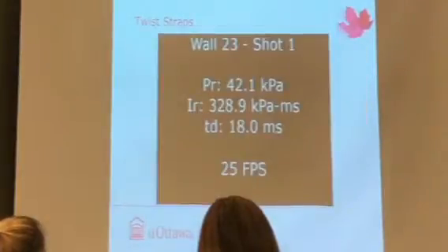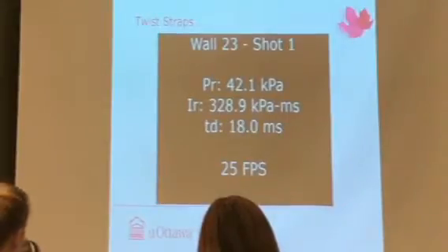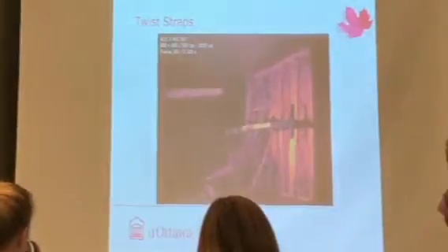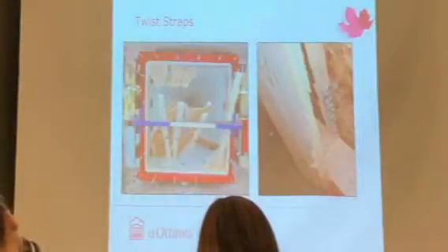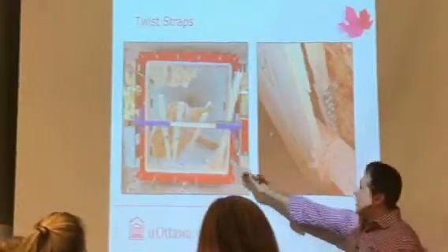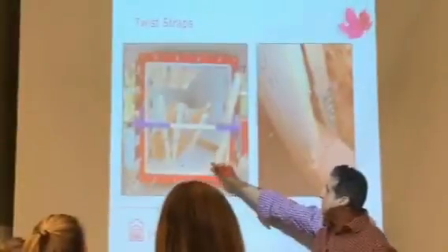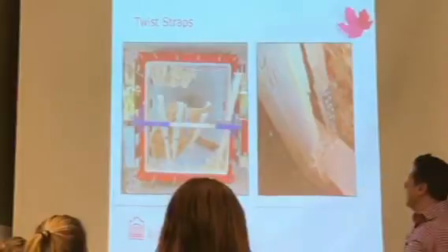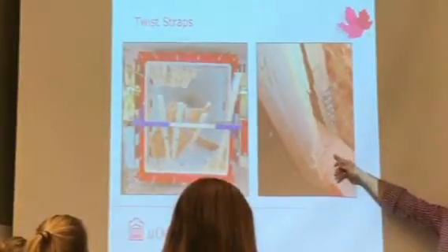This is the strap I was telling you about before, my favorite connection. And you see how the end gets detached first. All the studs fly out and they break in the middle because we have this system, so you know they don't fly away. But otherwise, the studs would just have flown away. So I was wrong again. And you see it here. You see when we compiled all the material in here, well, maybe this is from another test, they just hit the bracket and just laid there. But you see how the failure happened in splitting rather than in tension. Right? Should have known.